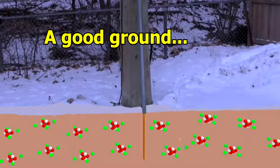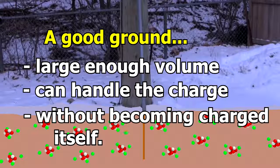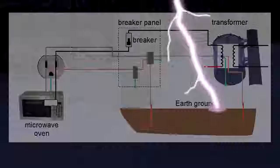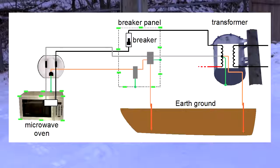So what's a good ground? A good ground is one that has a large enough volume that it can handle whatever charge you're trying to give it without it ever becoming very charged. Now back to why we're connecting wires all the way to earth ground. One reason has to do with lightning. Remember that the breaker panel case is connected to ground, and so is this microwave oven's case. When lightning strikes nearby, those cases can become charged. By connecting to earth ground, that charge bleeds away to the ground, keeping the cases safe to touch.